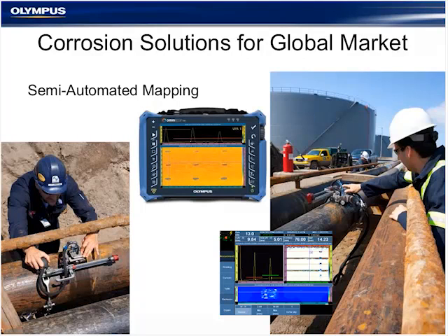This particular chain scanner will allow you to wrap around the pipe, so we will essentially flatten it and draw a C-scan map around the circumference of the pipe in roughly a 2-foot wide swath.